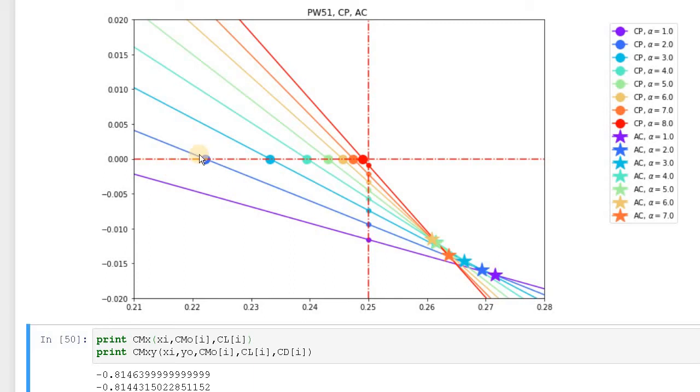What else? If you look at this graph, you will see that there are some interesting points. For instance, when the moment is equal to 0, obviously this point is a bit different for different angles of attack. Why different? Because you have different moments for different angles of attack given to you by XFoil. Different moments mean that you would have a different position for the point where you have the 0 moment. Those points are called center of pressure points. So you have center of pressure points located on the x-axis, and you also have interesting points where those lines are crossing. Those points are called the Aerodynamic Center. For whatever reason, let's assume that there is only one point, but actually those points are more or less closely packed, and you can look at the area of those points as the Aerodynamic Center of the airfoil.